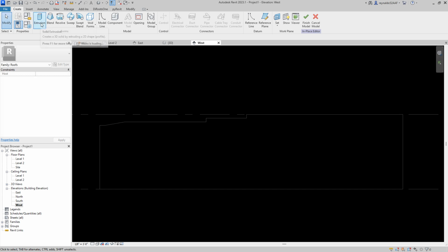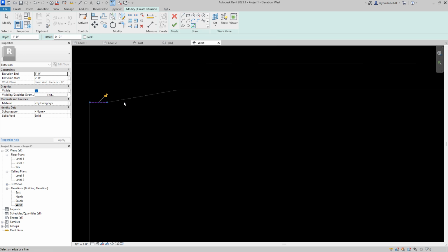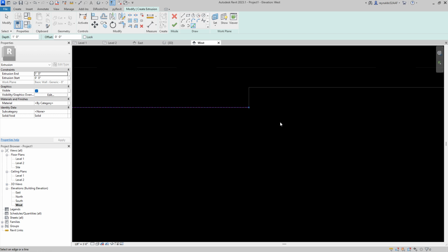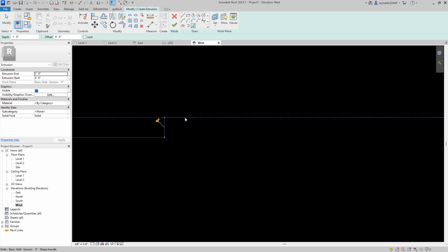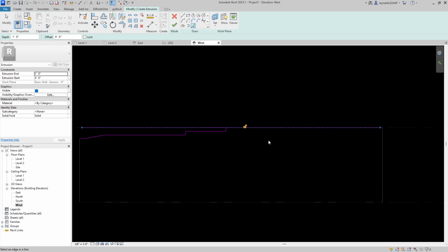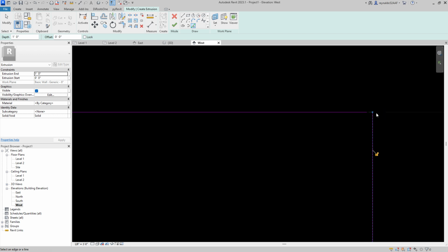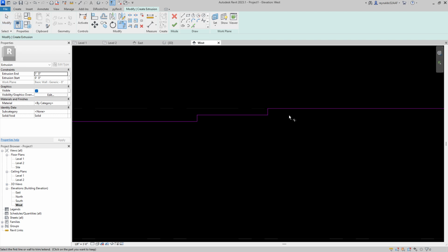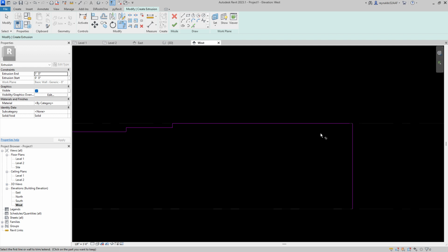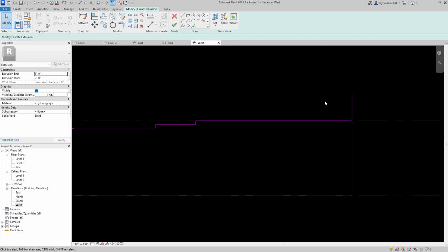Once I do that, then I'm going to click on the extrusion option, and then I'm going to click on the pick lines option, and then just click on the lines I want to trace quickly, just like that, like that. And then we'll extend it past over here. So now that we've done that, I'm just going to trim this. And well, let me delete this line. Well, I'm not going to delete it. I'm just going to extend it up like that.